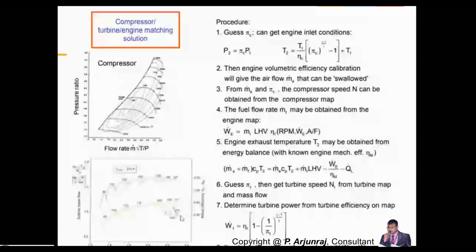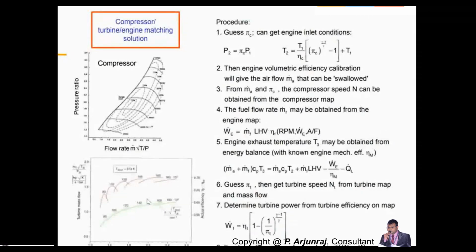And you see here again, you need to look at, suppose you find the pressure ratio 1.8 and the mass flow rate as 1.5, then you need to select the actual efficiency considering the relationship between the compressor and the turbo. You need to select based on the temperature, the fuel flow rate, and also the mass flow rate. So here there is a big procedure.